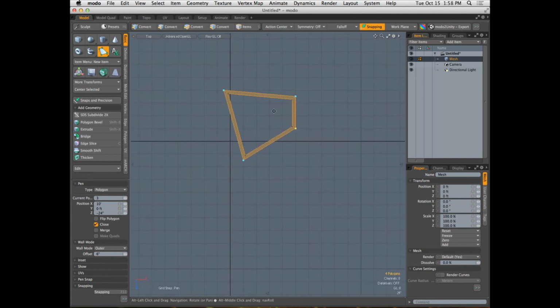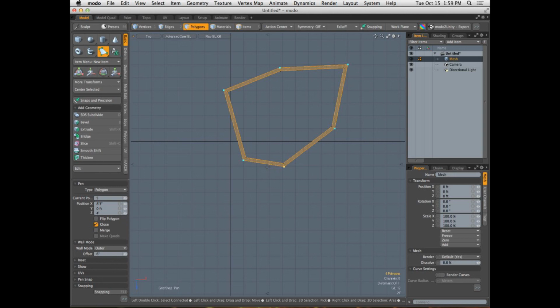It's a toggle, so if you wanted to deactivate the snapping system, just hit the button again. The pen tool will stay active, which is kind of neat. Boom. So we can turn it on and off at will. Now the snapping engine isn't being evaluated within my scene. I can turn it on while the pen tool is still active, snap to some other points, turn it off, and now I can continue defining and working with these points without the snapping engine on at all. So it's a really flexible system, and I like it. I like it a lot.